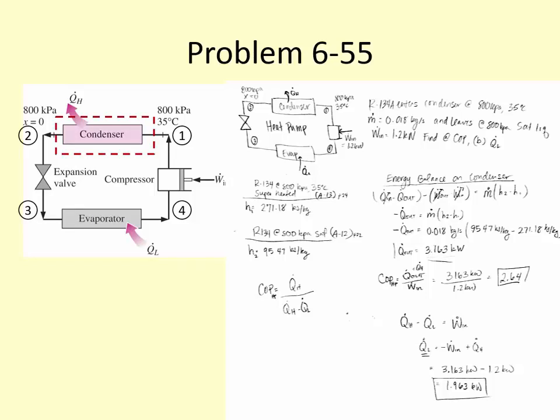So pause in your mind this talk about heat pumps, and just go back to Chapter 5. How do we find the inlet conditions for a condenser? We know the fluid, right? What's the fluid? Do we have anything that tells us about R134a? Tables, right? So let's go to the tables and see what is the inlet condition of this condenser. So at 800 kilopascals and 35 Celsius, what do we have? Make sure you're looking at R134a and not water.